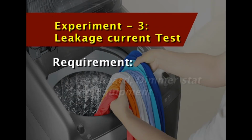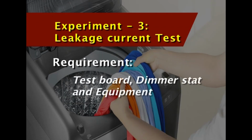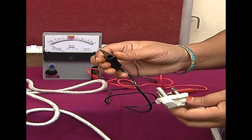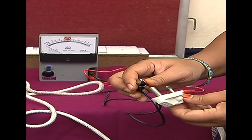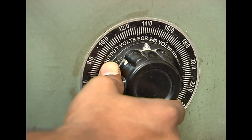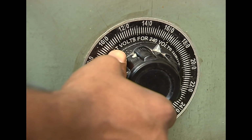The next experiment is on leakage current test. The aim is to find out the leakage current of the equipment. The materials required for this are test board, dimmer stat and equipment. The procedure is, connect the equipment inlet and the 3-pin socket provided for leakage current test. With the help of dimmer stat, adjust the voltage to 230 volts AC.